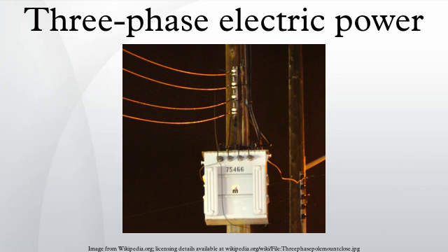While a single-phase AC power supply requires two conductors, a three-phase supply can transmit 3 times the power by using only one extra conductor. This means that a 50% increase in transmission cost yields a 200% increase in the power transmitted. Three-phase systems may also utilize a fourth wire, particularly in low-voltage distribution. This is the neutral wire.